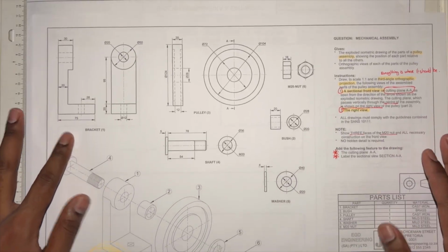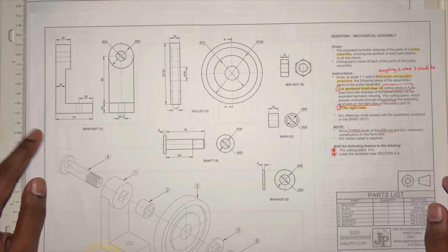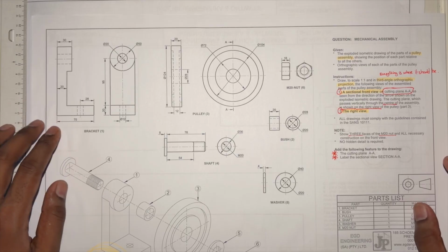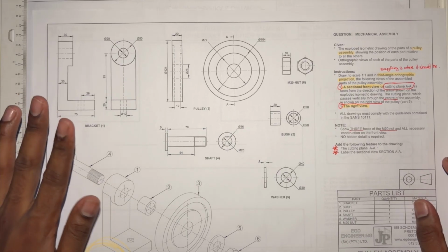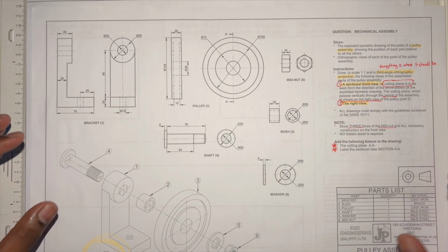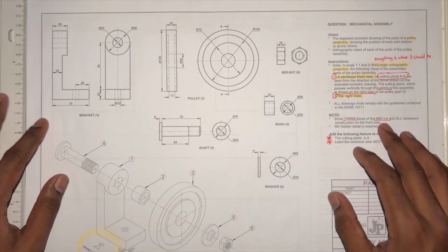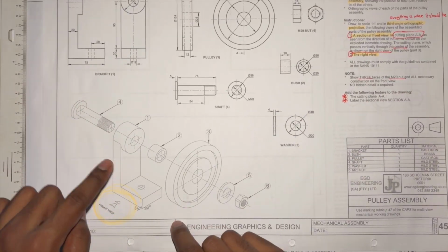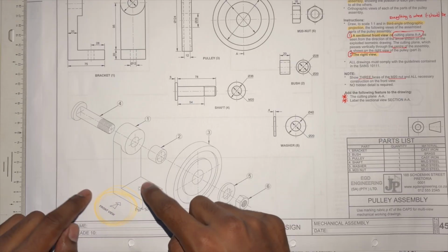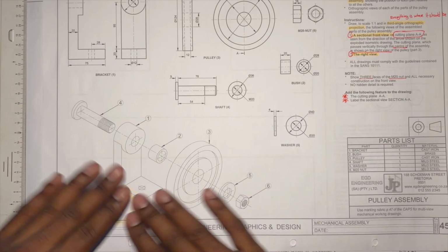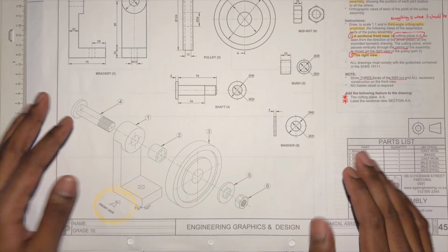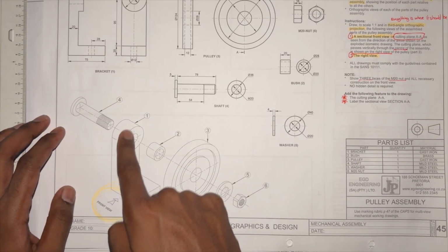Okay, now what I always tell my students, shout out grade 10 line 6, is that you should always start with the largest object, or in terms of drawing, start with the object that everything fits into. Okay, so if we're looking at this isometric here, we can see that everything fits into or onto this bracket. This bracket is seated or bolted to a flat surface, okay, using that bolt attachment there. So everything fits into this bracket. So that's what primarily I should draw first.